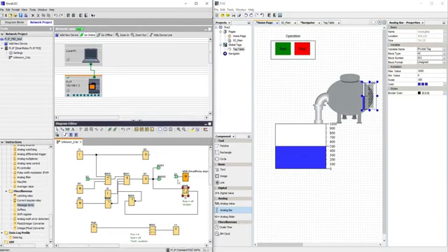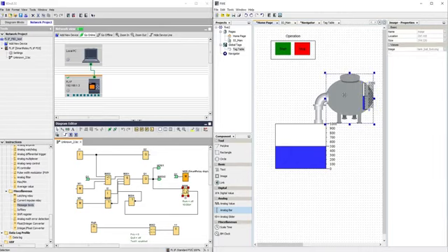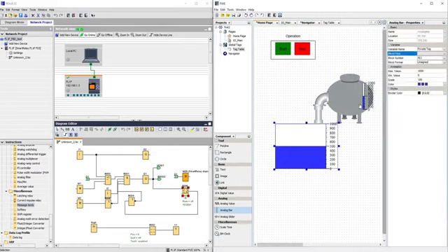So whenever we are starting a motor, let us consider we are filling water from one tank to another. So in this case, I have considered a timer. Whenever I'm starting the operation, let us assume a motor is there here and it's passing water from one tank to another. So in that case, water has to empty here and it has to fill here. So now we will be mapping these two analog bar values to variable memory. So in this small program which I have designed here, for the timer, I'm considering TC and TR, that is current timer and remaining timer.